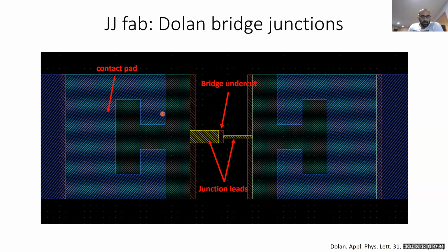So I am depositing along this direction, and that will ensure that I have deposition along the sidewall of my metal here and also here. But when I deposit along the other side, I will still have deposition along the sidewall here, and here, and here. This notch basically allows good electrical contact regardless of which orientation I'm depositing from.